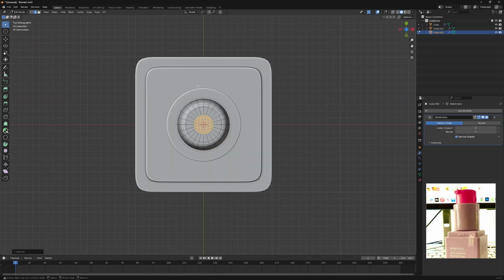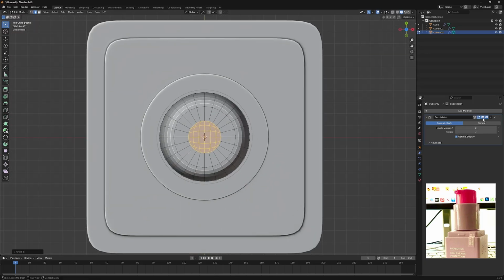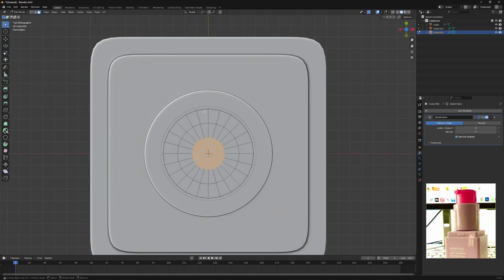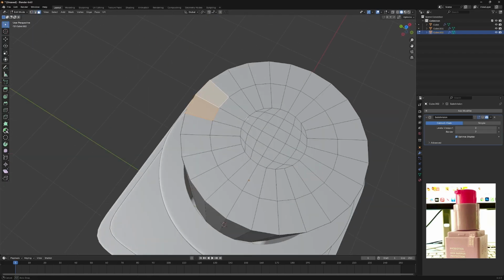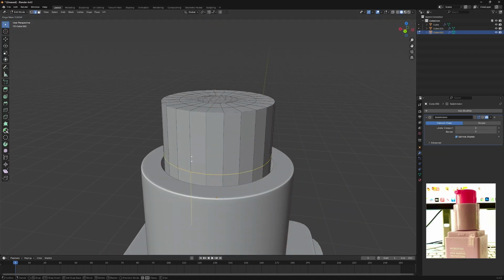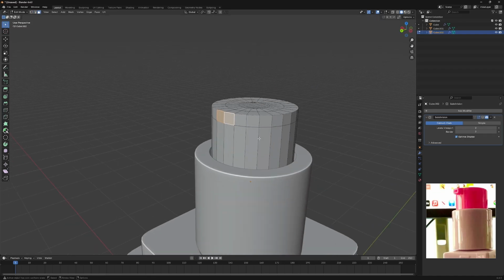Next, switch to the top view so that we can see where the opening will come out from. We can select these two faces. Add a loop cut and then drag it up. Select both faces and extrude towards the Y direction.